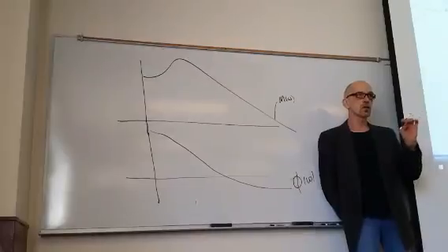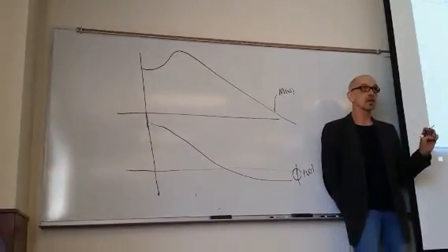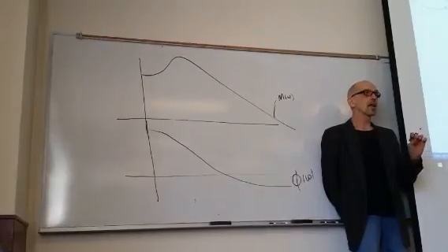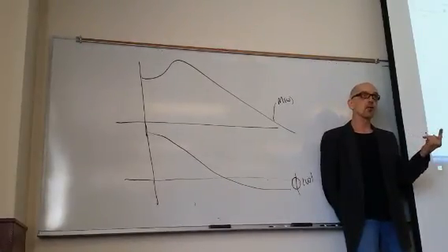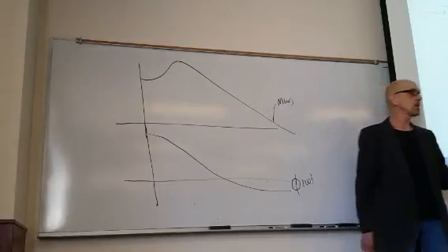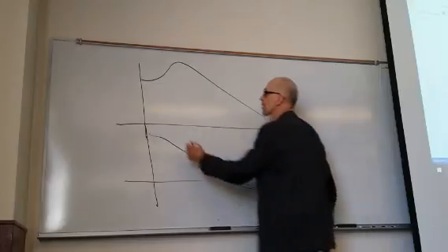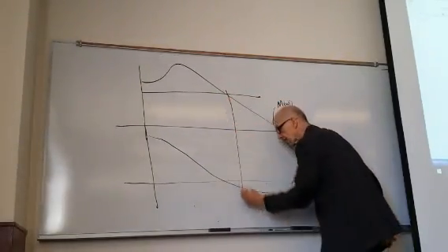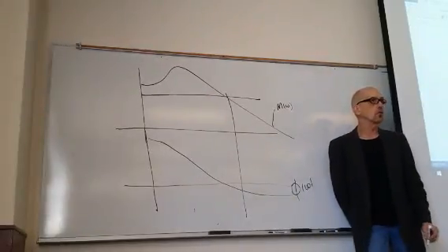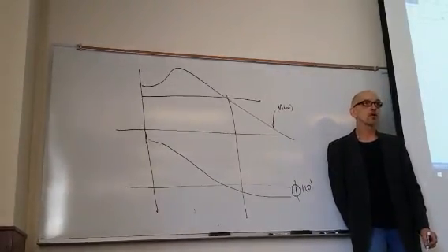In the first case, you say, all right, I want you to now design it. You've already established your steady state error, right? So this has to be a unity static gain compensator, so that when you let S go to 0, it's 1, and you don't mess up your error, right? So we're on that page? Okay. So then what you do is you say, let's get the current phase margin of the closed loop. Step 1, get the current phase margin of the closed loop.